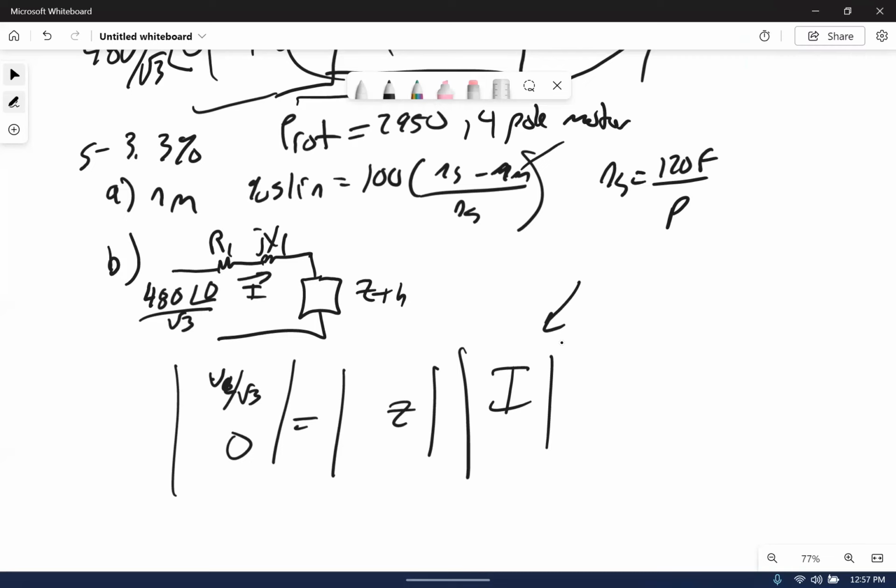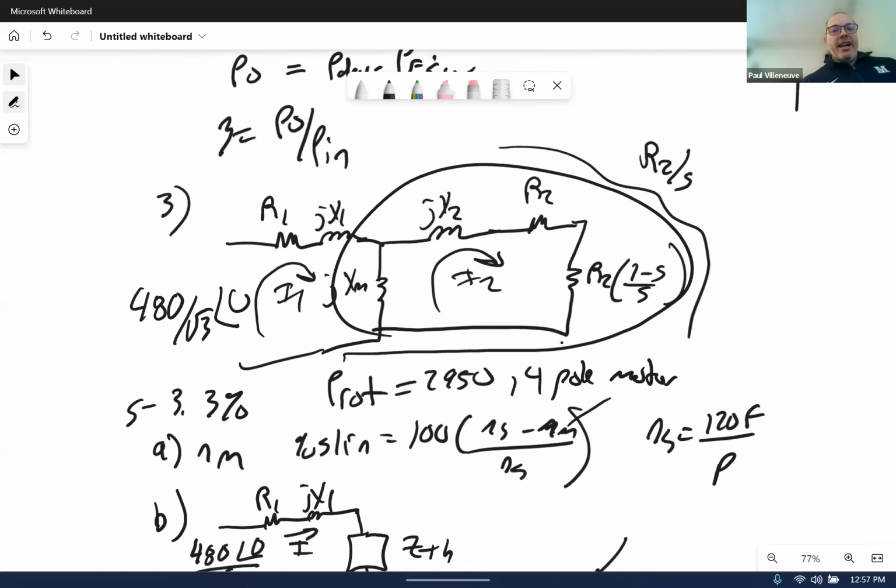We have computers that can do it. Computers will do that. If you ask a computer to go ahead and figure out if something's in series and parallel, it can't look at that and see that they're in series and parallel. What a computer will do is it'll just say, oh, I have a node over here. That's node 1, node 2, node 3, node 4, node 5, and basically do nodal analysis to solve all this stuff. Because having something that's got 10 million nodes is no problem for a computer. For us, it's a lot of work, but for a computer, it's no big deal.